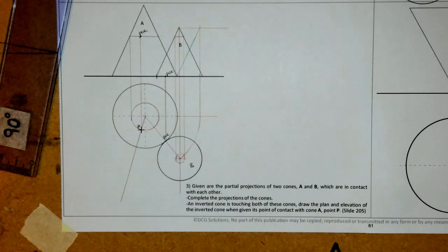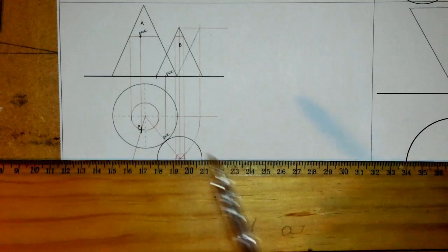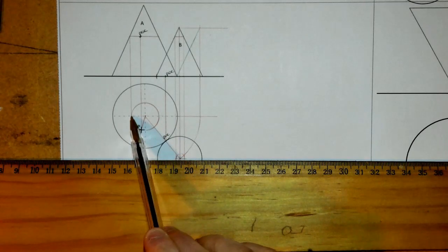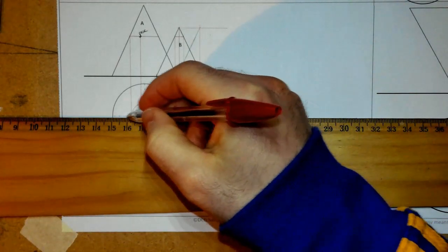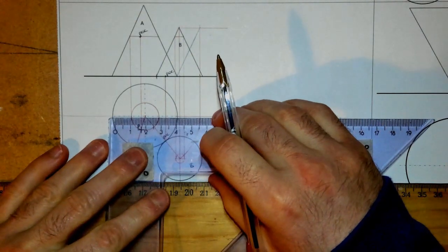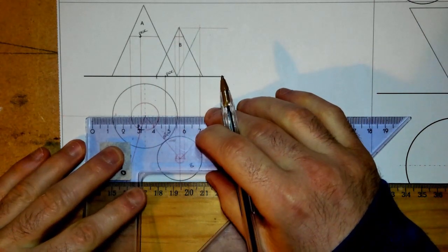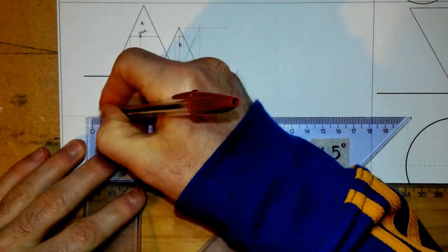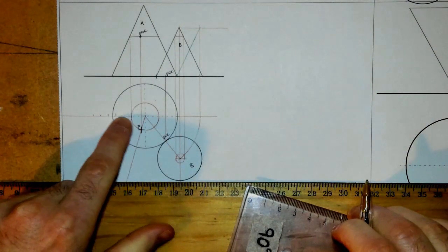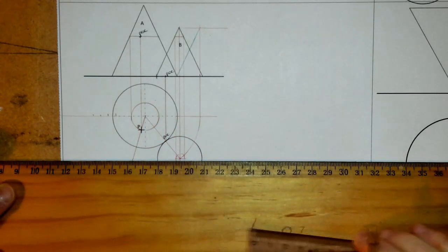So at this point now, we're going to take equal distances out from cone A and cone B, but we're not going to take them from the bases, we're going to take them from the horizontal cuts this time. So I'm going to take distances out, and the first one I'm going to do is 10, and then I'm going to do 5s after that. I'm going to do 5, 10, 15. So that's the first 4. So I skipped 10. I could have done 5, 10, but I just skipped the first one, and I'm going to do the exact same at this one here.